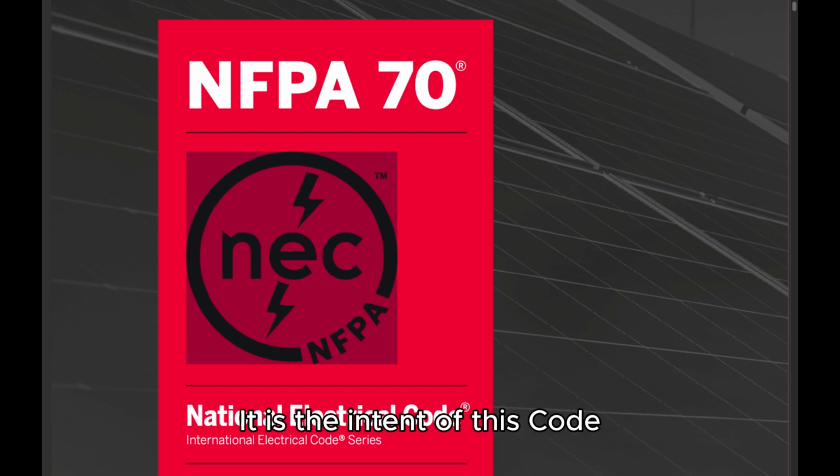It is the intent of this code that factory-installed internal wiring or the construction of equipment need not be inspected at the time of installation of the equipment, except to detect alterations or damage, if the equipment has been listed by a qualified electrical testing laboratory that is recognized as having the facilities described in the preceding paragraph and that requires suitability for installation in accordance with this code. Informational Note Number 1. See requirements in 110.3. Informational Note Number 2. Listed is defined in Article 100. Informational Note Number 3. Informative Annex A contains a list of product safety standards that are compatible with this code.